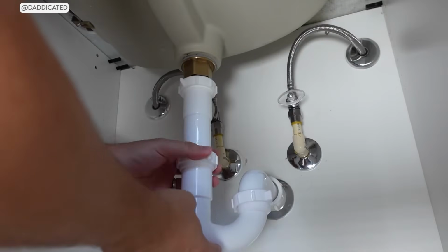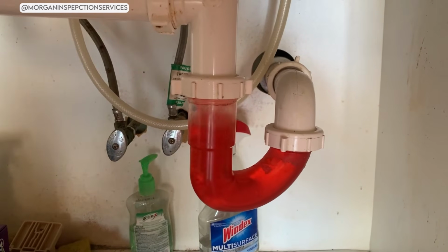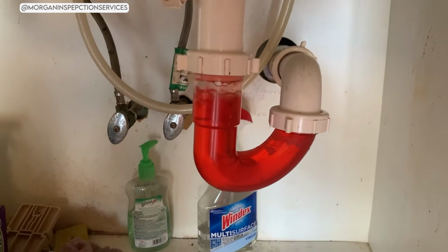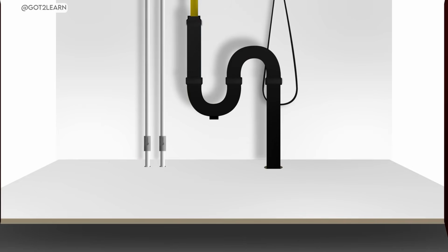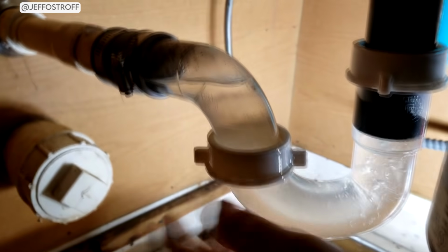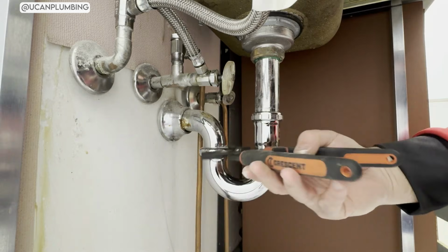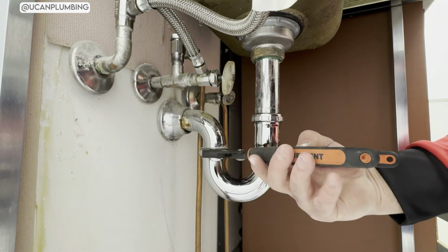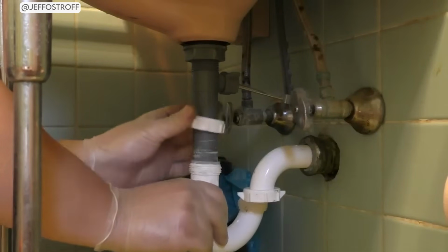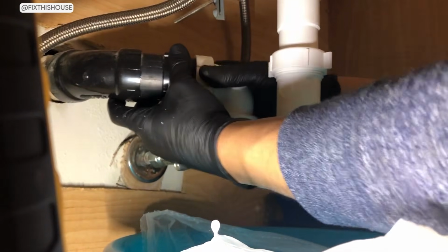The seventh thing every homeowner should understand is the P-trap difference. A P-trap is the code-approved alternative to an S-trap, and the difference is straightforward. Instead of the drain line curving downward into the floor after the trap bend, a P-trap sends the drain line horizontally into the wall. If you look at it from the side, it forms the shape of the letter P lying on its side. That horizontal section after the curve is called the trap arm, and it is the critical piece that makes everything work.